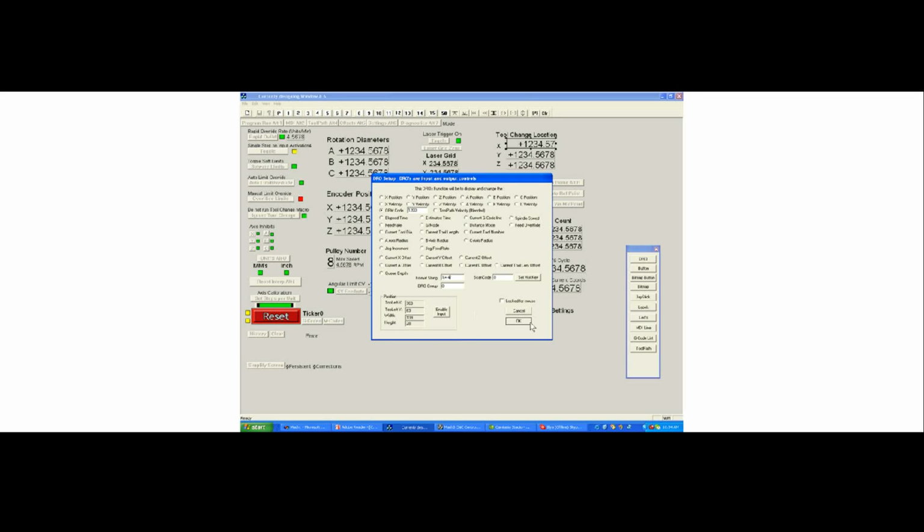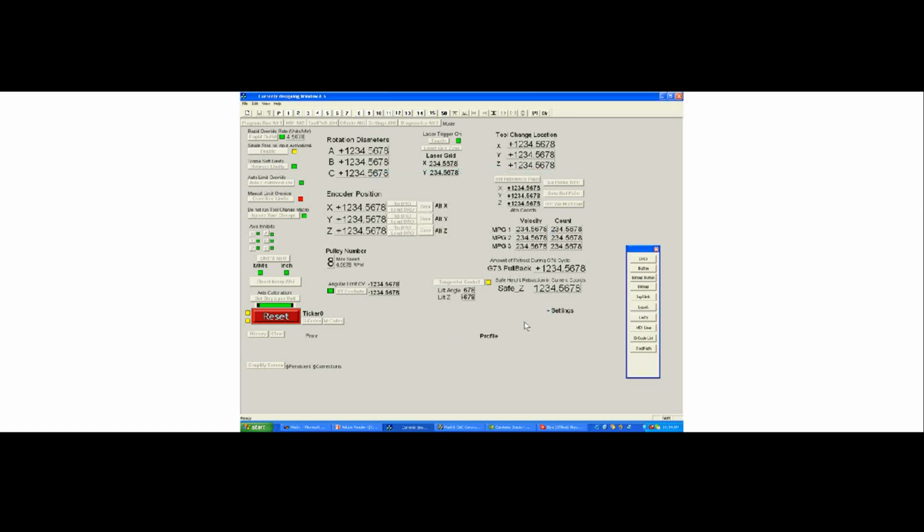In CNC, you normally would want 4 places of resolution after your decimal point. I should note that the program really doesn't care how you display it. It will always use up to 12 to 15 decimal points for accuracy. But these are display issues, and most people want that warm and fuzzy feeling they get from seeing the full 4 decimal places after any number.